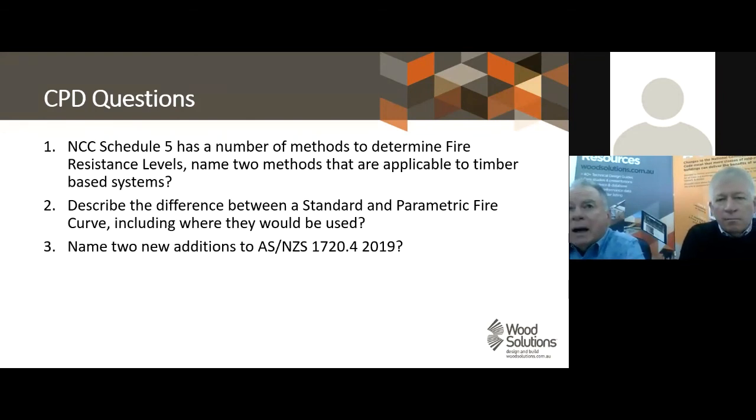Okay. This has happened in the past. There have been several occasions where, for different reasons, the Australian Building Codes Board hasn't accepted or hasn't been able to include a new Australian standard. It might be a scheduling matter where the standard had to be produced by a particular date in order to be adopted by the next edition of the NCC, or there was an inconsistency in the content of a new Australian standard with something that's in the NCC. But the important thing is you can still use the new standard, but you would have to use it as a performance solution.